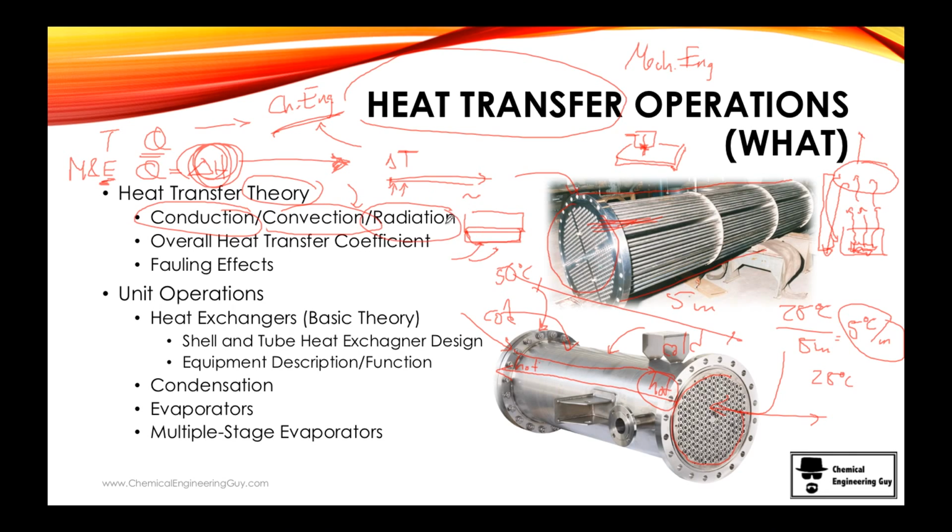And radiation. If you've been doing barbecues, you have your barbecue with these little metals. We have three types of heat transfer. I'd say 5% or less is conduction via these little metals touching the meat. Maybe 10% is convection, the very hot air that goes up. And the rest, 85%, is radiation, because the coal is very red.